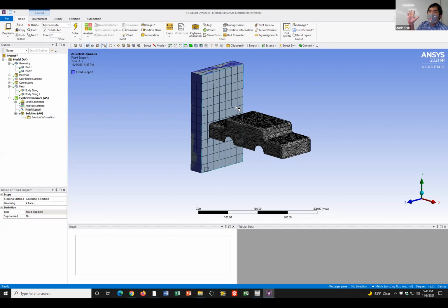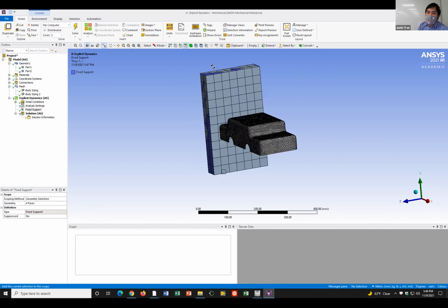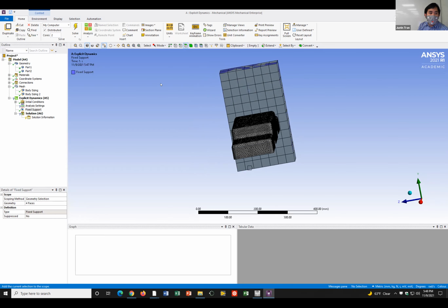If you hit an object against something else, it depresses a little bit. It may not be noticeable to the eye, but we have to give it that flexibility, because if we make a fixed support, we're basically going to have a perfectly rigid wall right here. And numerically, that can cause some issues. So we want to give this wall a little bit of flexibility for it to depress when the car hits it. That's another reason why we fix it on the side.